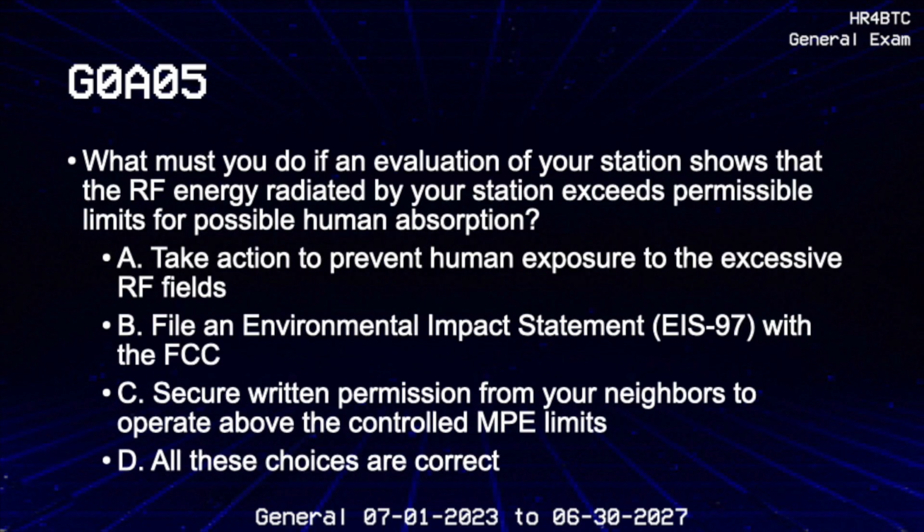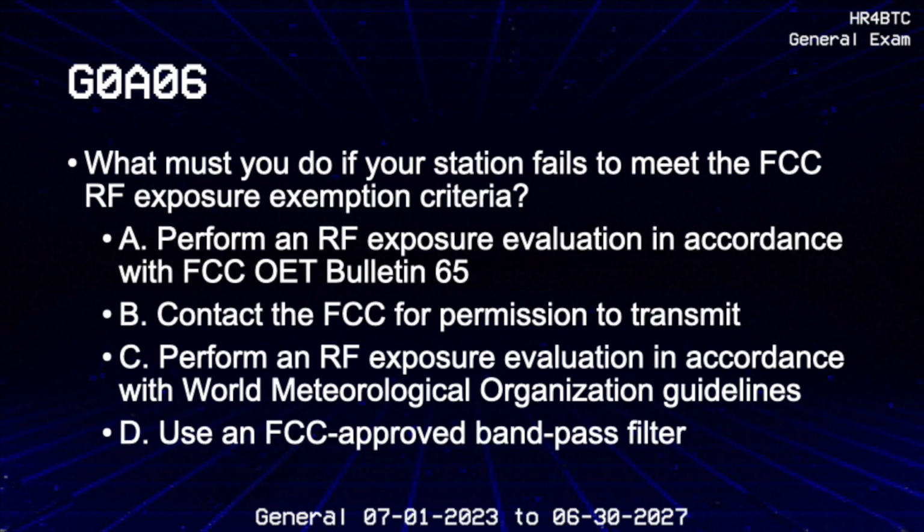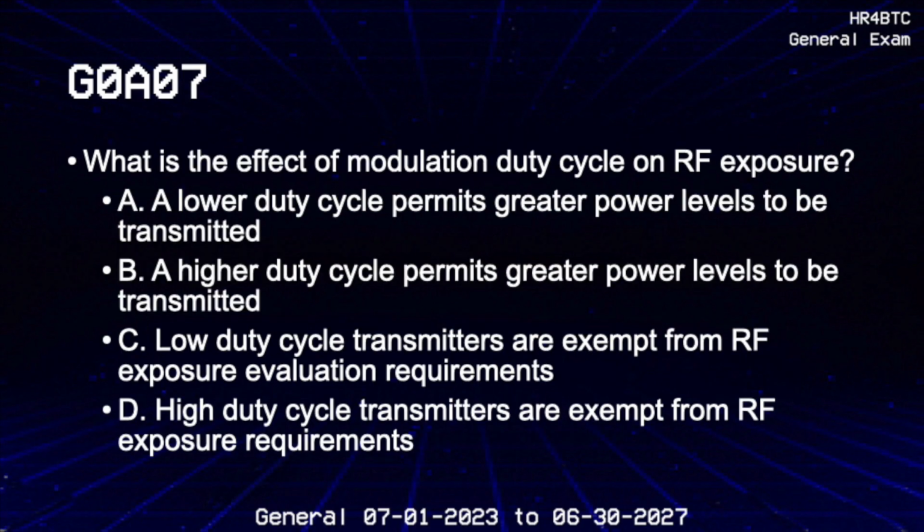What must you do if an evaluation of your station shows that the RF energy radiated by your station exceeds permissible limits for possible human absorption? Take action to prevent human exposure to the excessive RF fields. What must you do if your station fails to meet the FCC RF exposure exemption criteria? Perform an RF exposure evaluation in accordance with FCC OET Bulletin 65. What is the effect of modulation duty cycle on RF exposure? A lower duty cycle permits greater power levels to be transmitted.